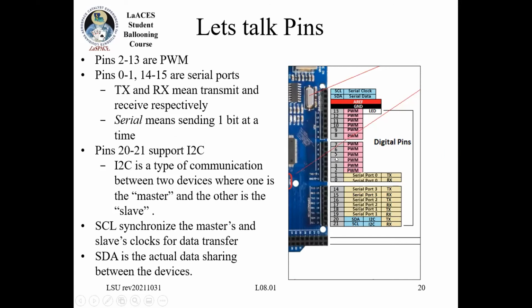So pins 2 through 13 are your pulse width modulation. Pins 0 and 1 are serial 0, but in the IDE it's just Serial.